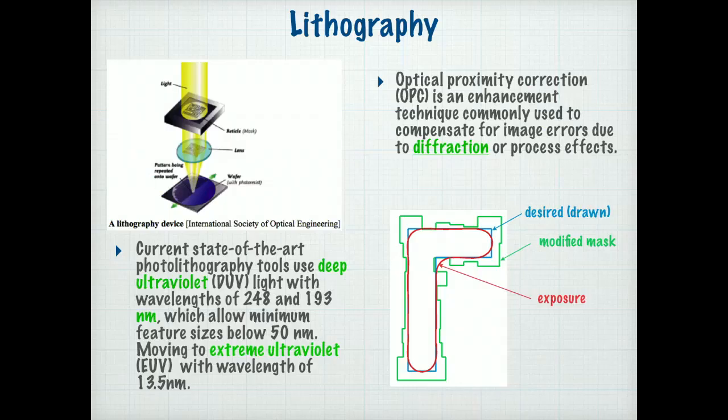As I said, the key to this is photolithography. There's some light source, UV light these days. It's focused through some lens down onto the surface of the wafer, and there's a mask that the light shines through and exposes the surface of the wafer. It's amazing how it works.